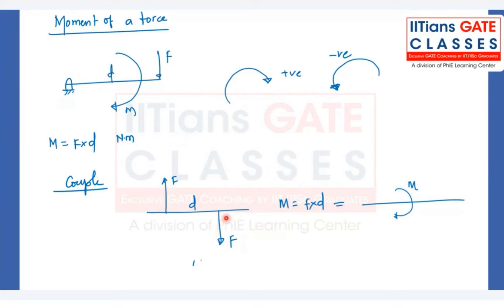So the value of couple here is again the same, F into D. F is the force and D is the distance between these two forces. You can clearly see this is creating a clockwise effect. Let me draw here. You can just imagine by the arrows of these forces how the turning effect will be created here. It is clockwise, right? So couple is equivalent to a moment F into D. The two forces of magnitude F in opposite directions, separated by distance D, are creating this couple.